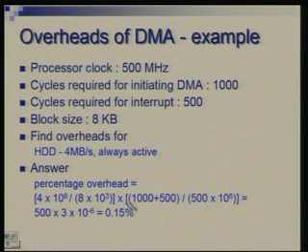And each time you do DMA, you are spending these many cycles, this in the beginning, this in the end, and divided by the clock frequency will give you the fraction of time spent on the DMA by the processor. Of course, the DMA controller has to do a lot of work. The work has been taken off or outsourced by the processor here.